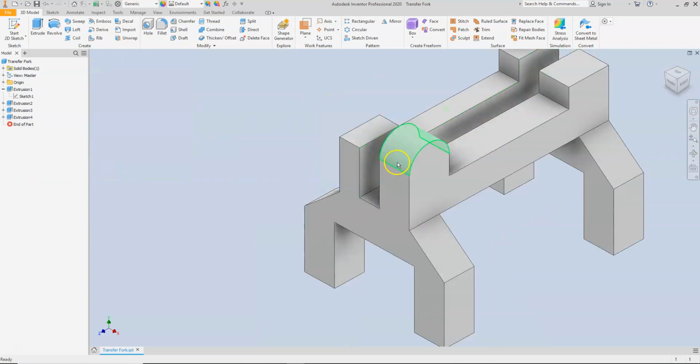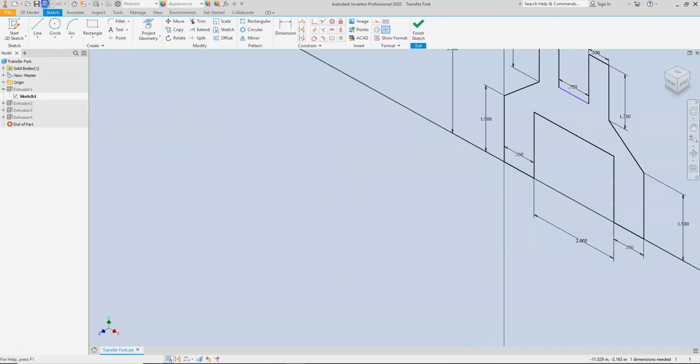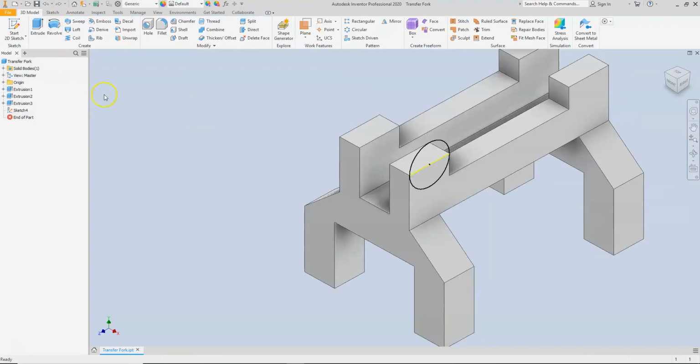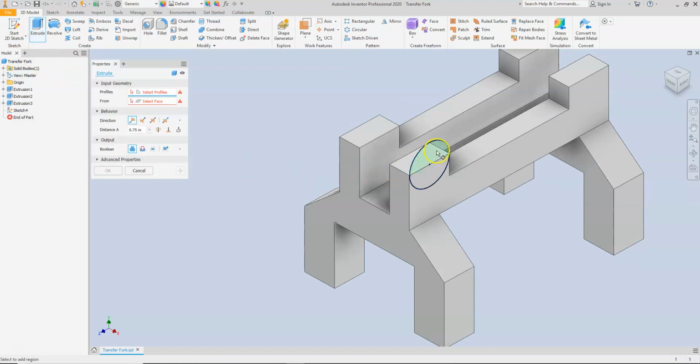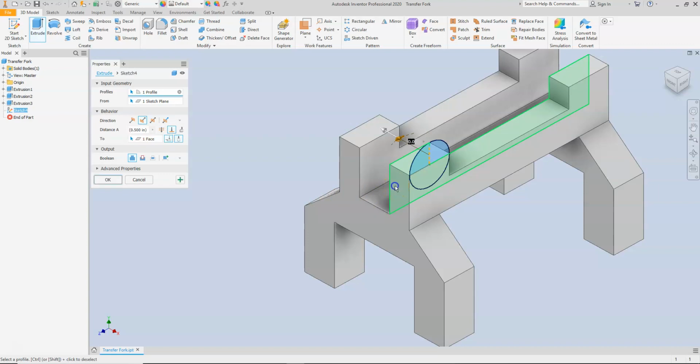Now, one time, probably not going to make much difference, but if you do this over and over on multiple drawings all day, it does make a difference. So that would be the long way of doing this. Now, if you chose differently, I'm going to back this up just a little bit. Going back to the extrusion, we extrude this here, changing the direction, but instead of using a dimension we use the To Next option, and we know that this part is relevant to this face right here.